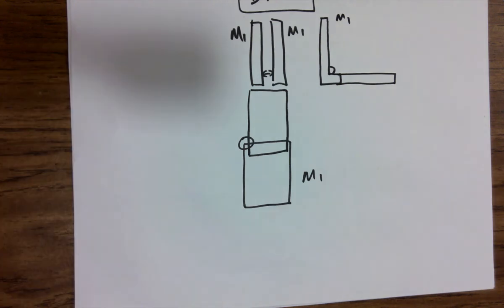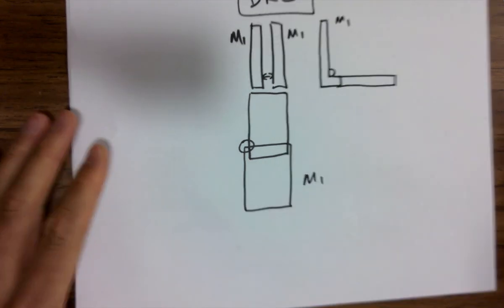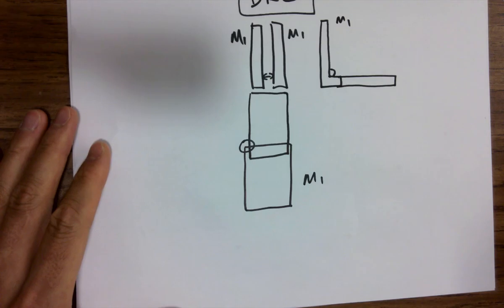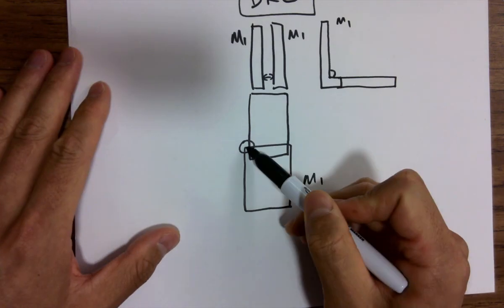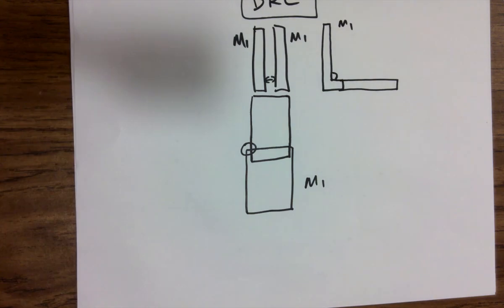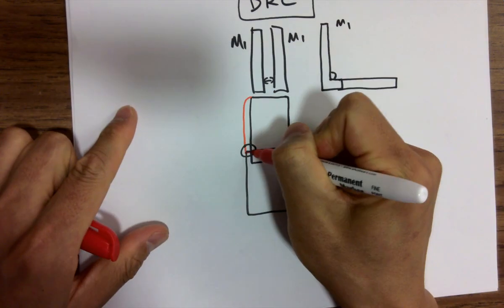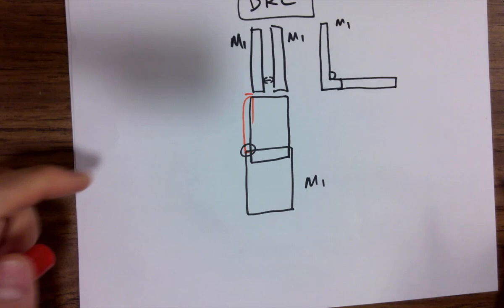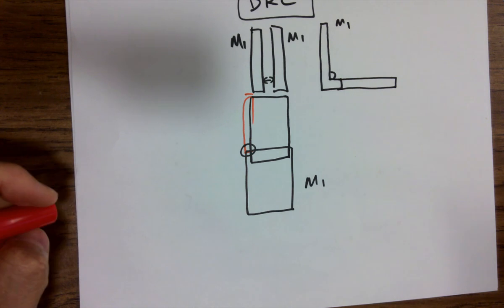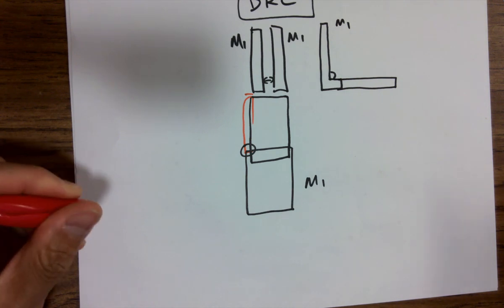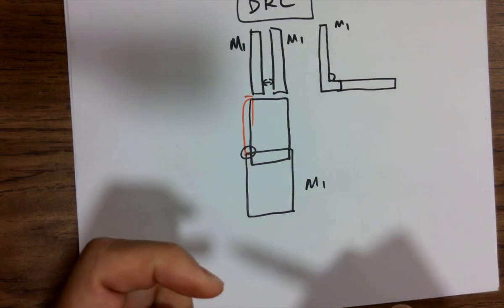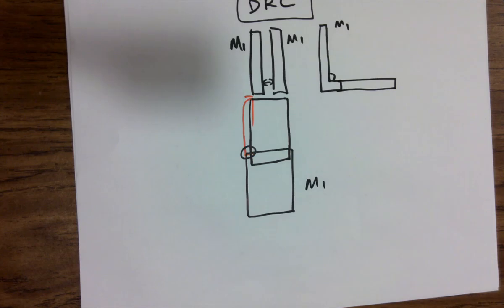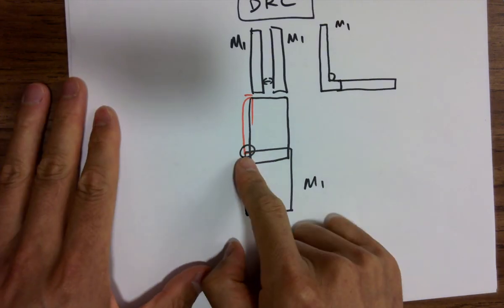The fab doesn't know this doesn't matter, but the tool is going to report an error. You know it doesn't matter because it's just metal, even though it's not being resolved, so the fab will eventually give you something like this. But the tool doesn't know that. The tool feels really bad about itself. It feels like it didn't do whatever you required it to do. It eventually cannot resolve this corner, but it's actually a bad design. It's on you, so something like this you're going to avoid.